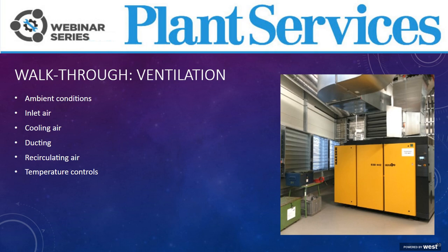We already discussed inlet air, but remember, it's got to come from somewhere. Typically, this is going to be outside the compressor room, as you can see in the picture on the right there. In this case, inlet air is going to come via a louver damper. These louver dampers also serve to bring in the cooling air that you need to keep an air-cooled machine within temperature. Air from outside also ensures this can provide proper cooling. However, in wintertime, you may need some recirculation of the compressor hot discharge air to mix with that outside ambient air if it's too cold outside. And you can see a recirculating duct just above that yellow compressor there, right in the middle.